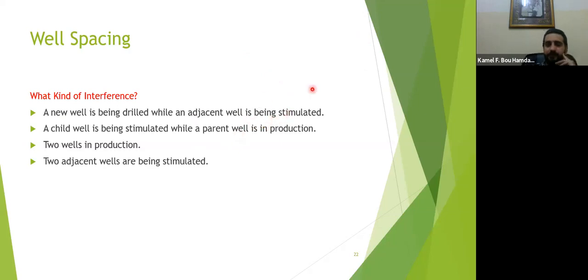So when this happens, your pore pressure while drilling is going to be different than what you were estimating. Everyone should know that when you are drilling, to place the casing and to choose your mud weight, you should look at the pore pressure gradient and the fracture pressure gradient.